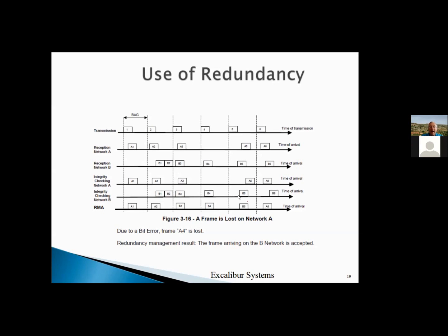And then if it comes back, I'll eventually use the A. And then if something gets lost in B, I've increased my chances by way more than 2, because it's true, I went from 1 bus to 2 buses. But since the likelihood of an error on either of them is very small, the likelihood of an error on both of them is vanishingly small. And therefore, dual redundancy really picks me up a great deal of power. Now, if I have a super, super sensitive bus, I can have quad redundancy as well. I use A, B, C, and D. And the same mechanism is going to work.